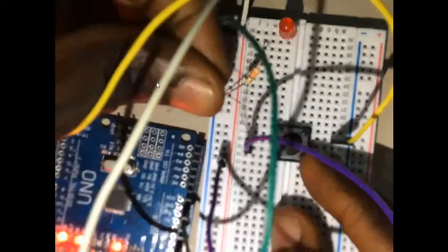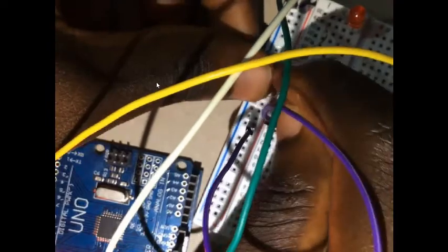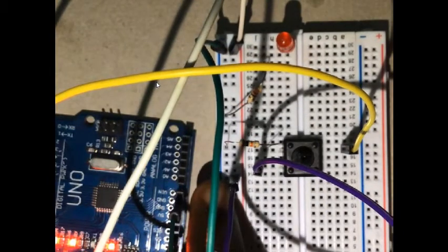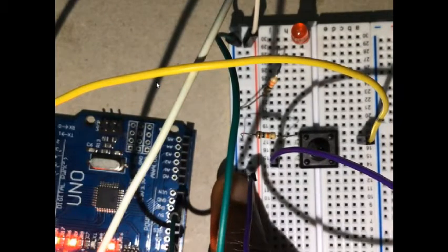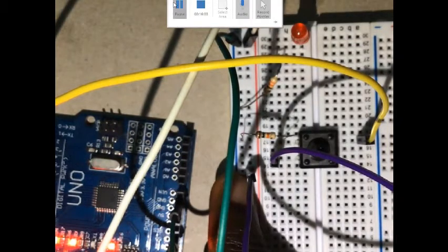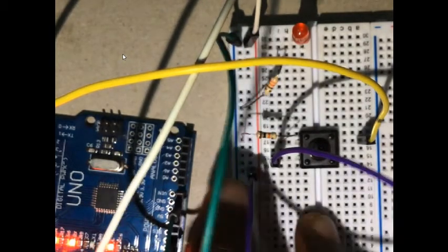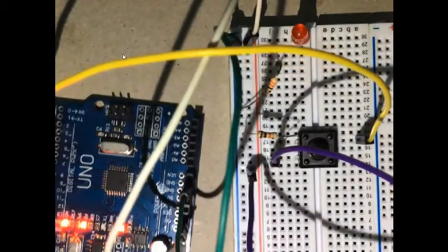Usually I call it bringing down that button or that pin to ground. So we connect it to ground, something like this. You can see that I have connected that resistor to ground. Okay, I have connected it like that, and this is a 10k ohms resistor. Anything 1k or 10k will do.